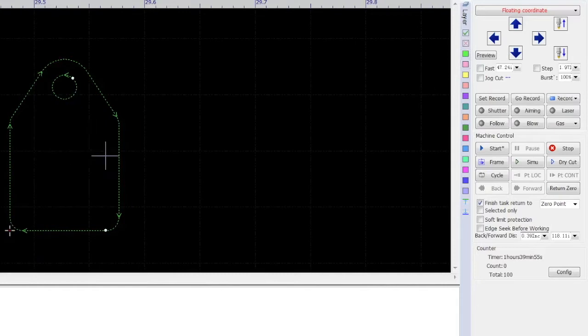So in other words, green might be 6mm steel, pink might be 10mm steel. So you've got a lot of presets where you can just click that color, once you get your library built of your common colors that you want to cut, or your thicknesses and material types that you want to cut. So that's a part of this layer setup here.